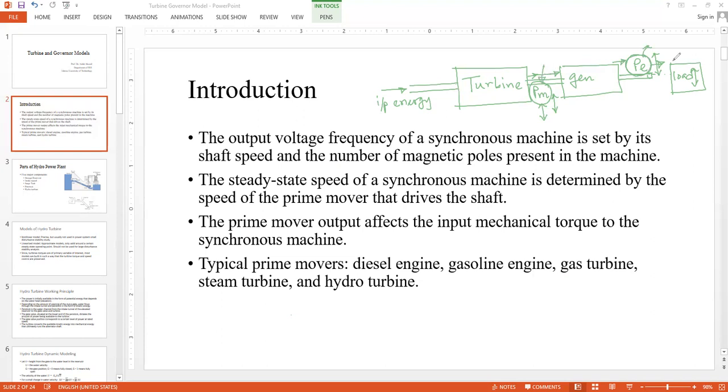And if we are not able to control the real power output, that means if the load is getting reduced, with P remaining constant, then for a reduced amount of load you have to incur some losses. On the other hand, if PE is constant and you are not controlling it from the input side, and the load changes in the positive direction, then with this PE you are unable to supply the demand.